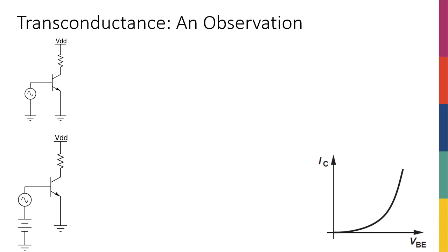So let's actually make that amplifier, because in the beginning of this chapter, if you go back to last week's notes, you will see that I claimed that if I have a voltage controlled current source, I'm going to have an amplifier, right? We saw the equations and we saw that if the relationship that governs the voltage dependent current source has a K that is large enough, we're going to get an amplifier.